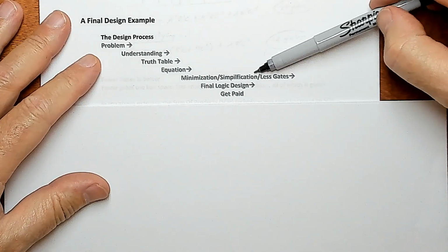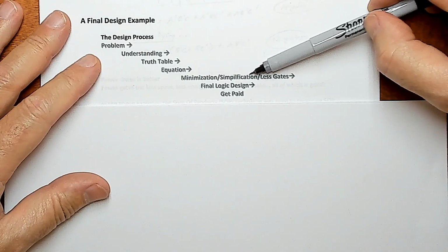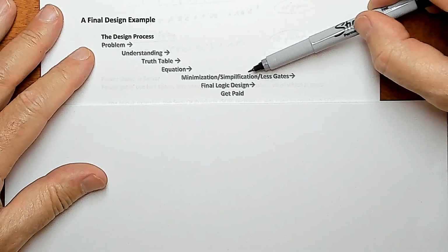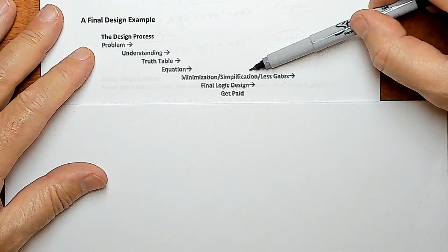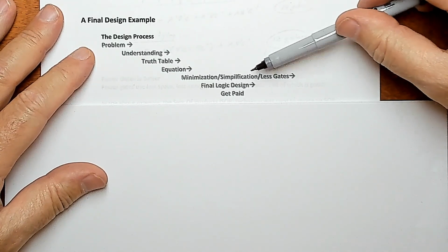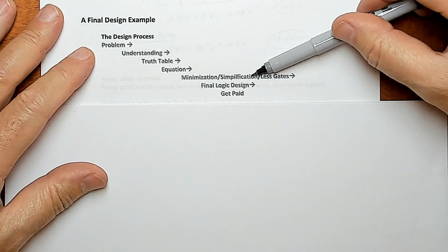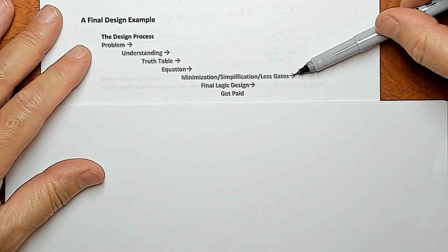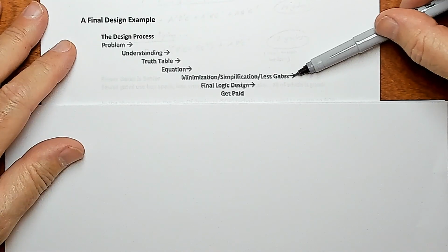Then we can use some Boolean algebra, and there are other simplification techniques. One is called K-maps, which is beyond the scope of this course. It's interesting stuff though. There's also something called the Quine-McCluskey algorithm. Those are the two that I'm familiar with; there are probably others. But you use these various simplification techniques, algebra, K-maps, whatnot, to get an equivalent circuit with fewer gates, because fewer gates is better if you're actually making something physical.